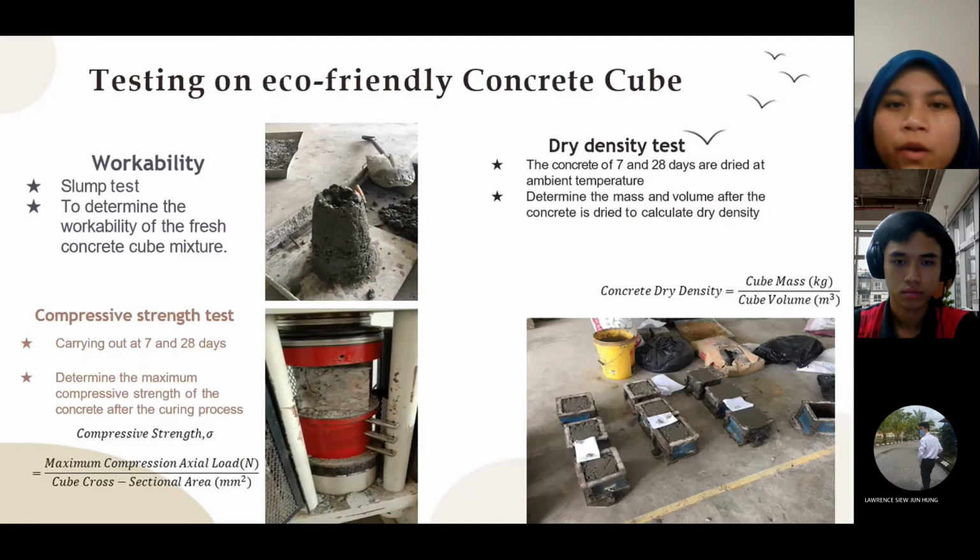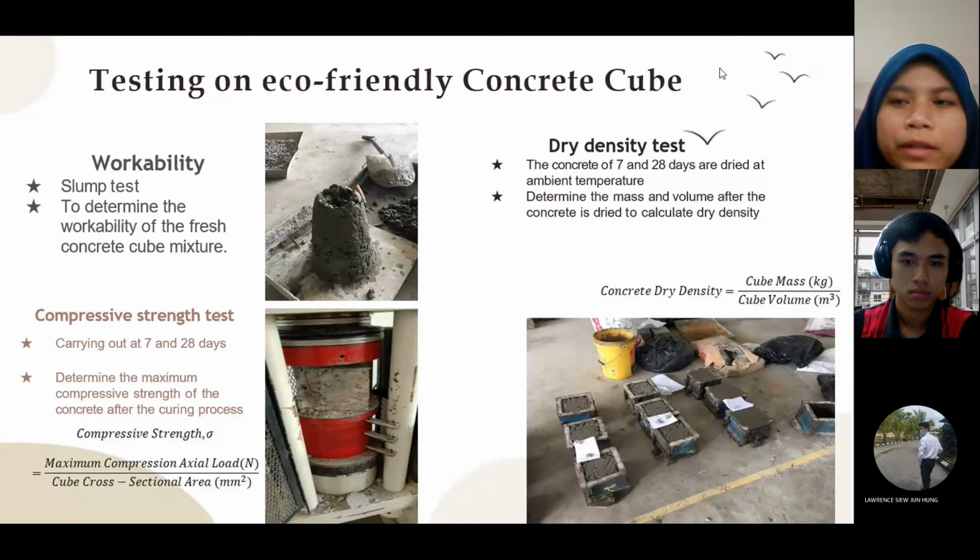For testing the eco-friendly concrete cubes, we do a slump test to determine the workability of the fresh concrete mix.